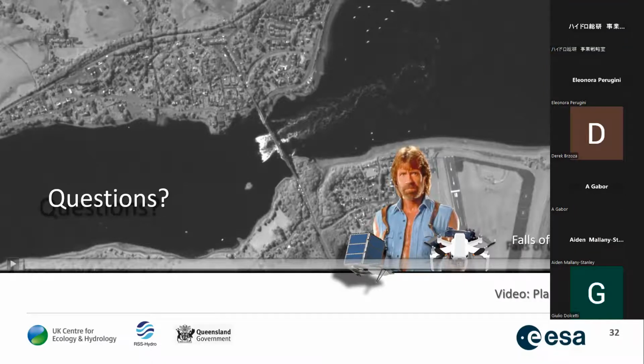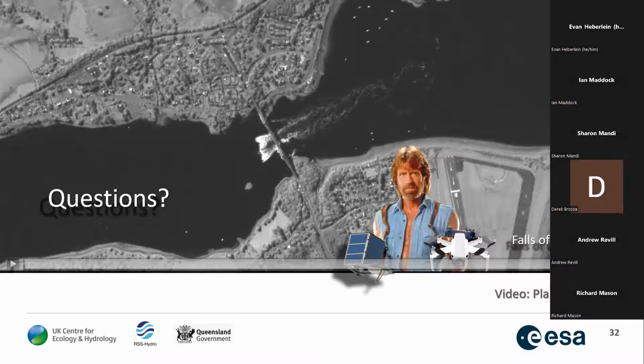And so the question was, and this challenge came from Planet themselves, could we actually measure velocity in rivers just using this? We have 0.3 seconds between the first time the river is imaged and the last time it's imaged. So that's our time separation. And it works if the river's flowing fast enough, and by that we mean 3 meters a second and faster. It can work. And my point coming back to cost is that's way cheaper. If we can make that work, it's way cheaper.